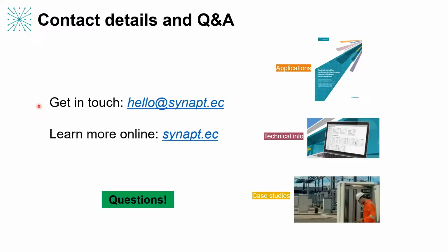Yes, of course. As you've said, Saul, the drawbacks to distance protection, particularly in this application where you have complex multi-terminal circuits, is that it will have some ambiguity on fault location, because there's a resolution associated with its location of the fault as a distance from the measurement point. That's why operators generally want to use differential protection, because if you can monitor the current into and out of each one of those terminals or each one of those zones, then you know with very high confidence whether a fault has occurred in that section or outside of that section.